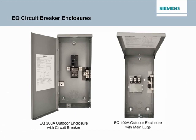Siemens EQ circuit breaker enclosures are designed for use with the QP, QT, QPH, HQP, BQ, BQH, HBQ, QPP, QPPH, HQPP, QJ2, QJH2, and QJ2-H circuit breakers. Both indoor NEMA 1 and outdoor NEMA 3R enclosures are available.